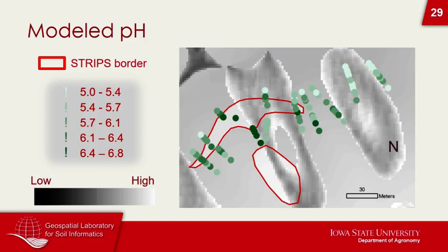So for the base data, we use a 2 meter elevation raster. So the size of the pixel was 2 meters by 2 meters. Once you do an analysis on that, you need a window. So the windows start at 3 by 3 and then move up every odd number. So 3 by 3, 5 by 5, 7 by 7.